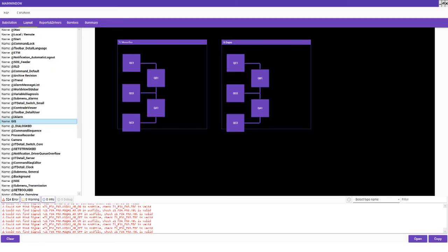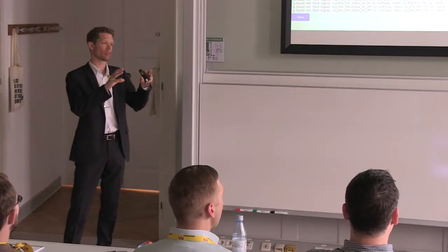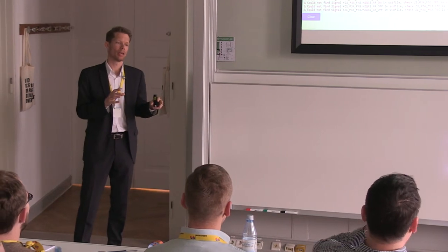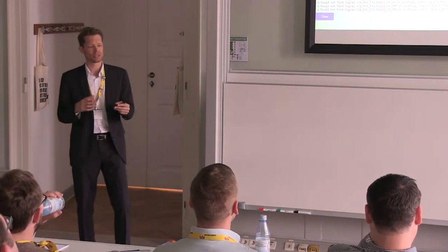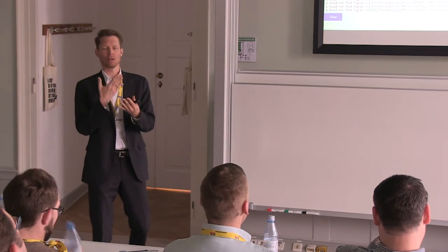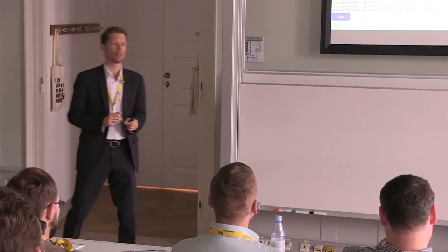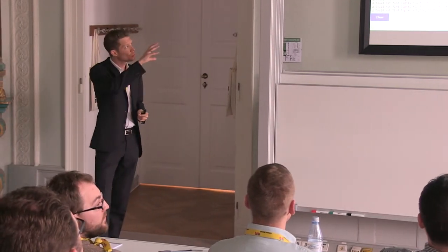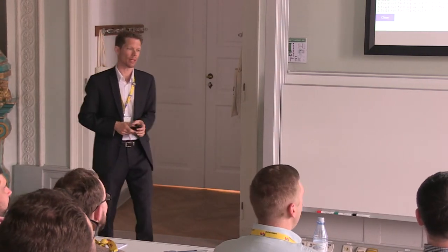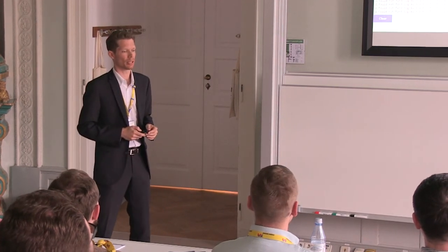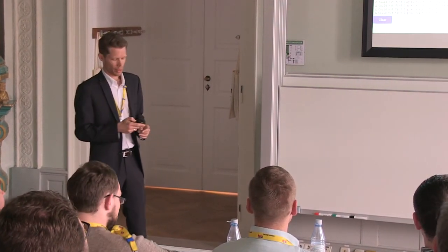And as there are no XY coordinates available in such a configuration, you would need to arrange all your boxes or diameters, or however you call them in that wizard, already. Otherwise, the wizard would place everything on top of each other at the same position, and then you have to rearrange that in the HMI editor again. So you can do that already here, and then you have a nice structure and see everything when it's in the HMI editor.